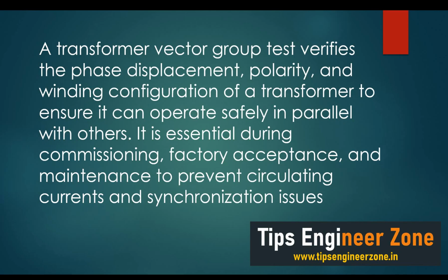A transformer vector group test verifies the phase displacement, polarities, and winding configurations of a transformer to ensure it can operate safely in parallel with others. This is essential during commissioning, factory acceptance and maintenance to prevent circulating current and synchronization issues.